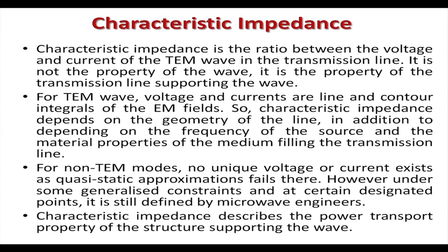Now, the problem is characteristic impedance cannot be defined for TE and TM modes. Only for the TEM mode it can be defined, because it is a quasi-static field, we can define a V and I. We have already seen that for non-TEM modes, no voltage and current exists, as the quasi-static approximation is not valid there, the Laplace equation is not valid.